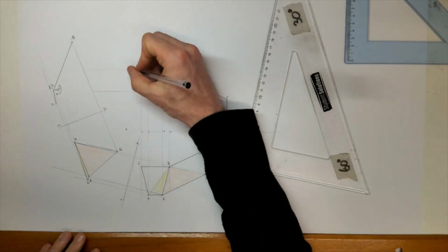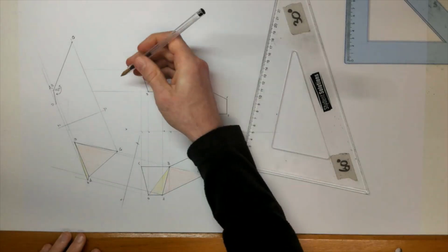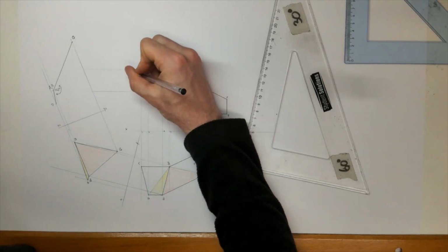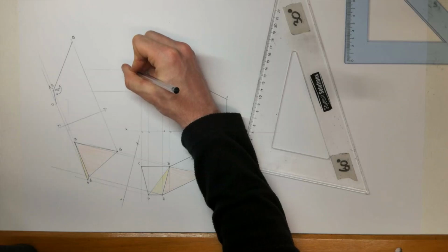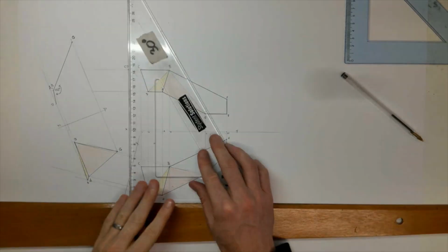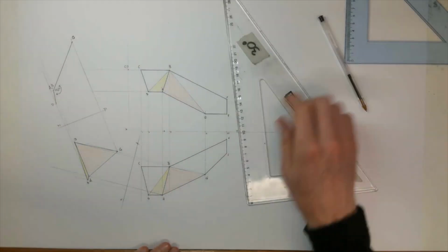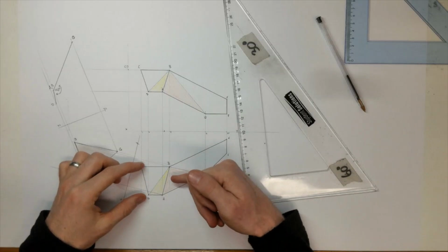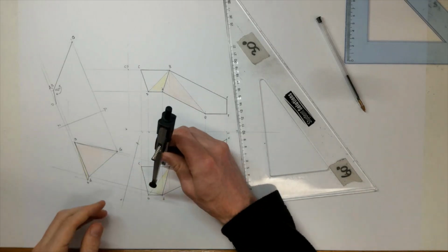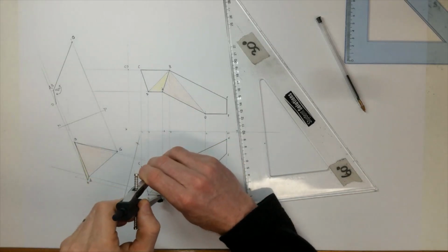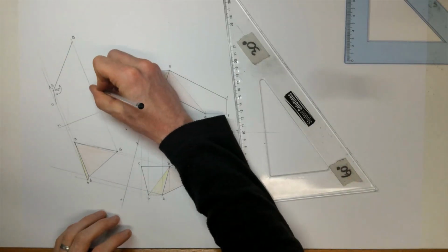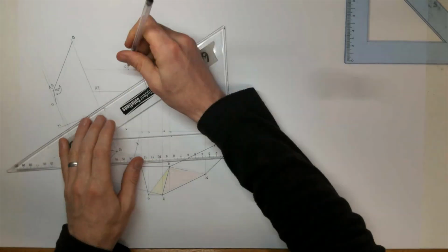So I'm going to situate CD, they've been projected there. I'm essentially creating an end view, kind of looking in from this side of those. So this is point CD, and AB will be out here along there. So they're actually going to create a little datum. So I'm looking in from here, almost like an end view. So that distance there, so that's the point view of A, D. Here we have an edge view of it.